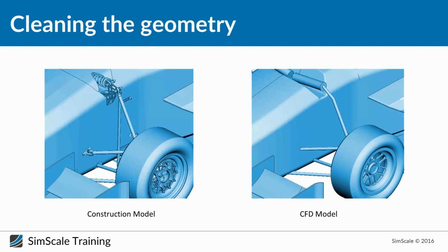If you upload your model as a STEP file or an IGES file to the platform, it will be converted automatically into an STL file, and then you have no control over the tessellation of your STL file. Therefore, I suggest to do it manually in your own CAD model. And very important is that if you export this whole model with all parts as one STL, in 99% of the cases, all faces will be fused together to one. Therefore, you have to export every patch independently and then merge the files later on.